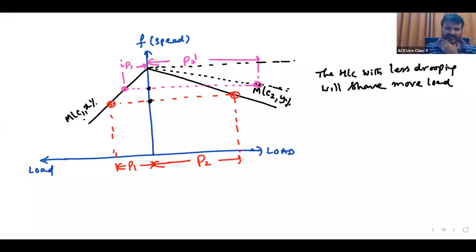These currents will exist definitely. If the mechanical power input of the first machine is increased, the synchronizing current is more. When excitation of the second machine is reduced, E2 demagnetizes and E1 magnetizes, so the difference will reduce. But that ISY keeps on existing always.